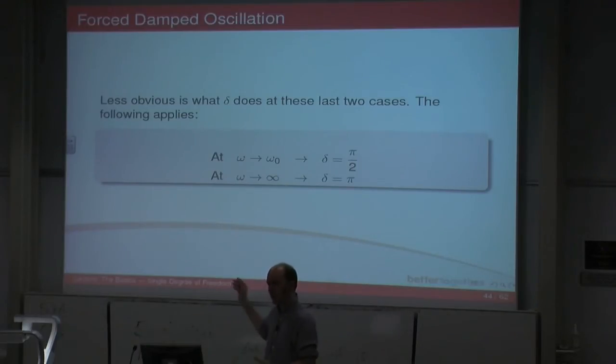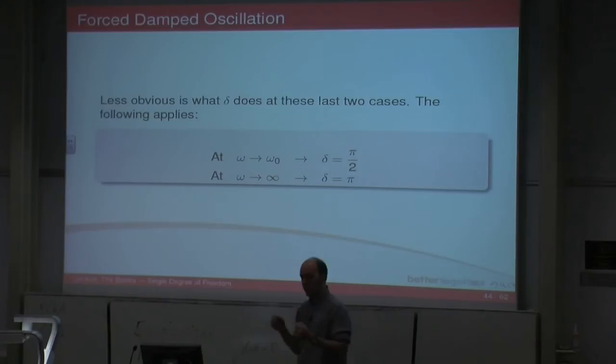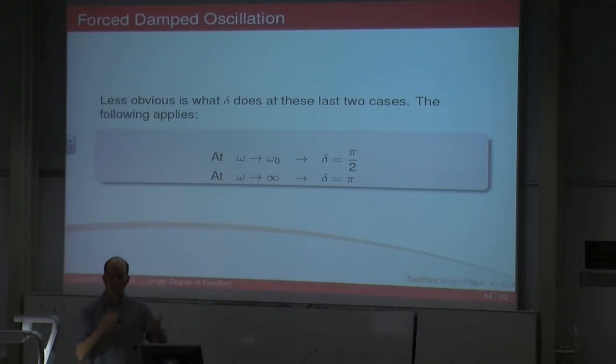And so in that case, if I go above my natural frequency in terms of the excitation force, my phase lag is going to increase, and it will increase to such a point where I end up with the thing being completely out of phase with my applied force. I'm applying a force this way, it's actually moving that way. Doesn't make sense, but that's the case.